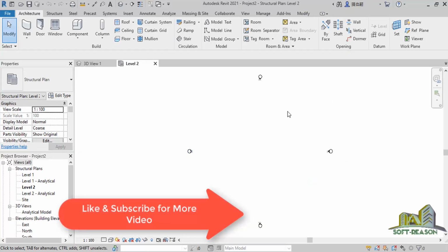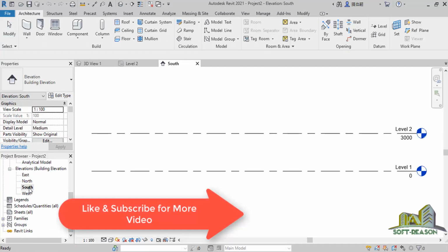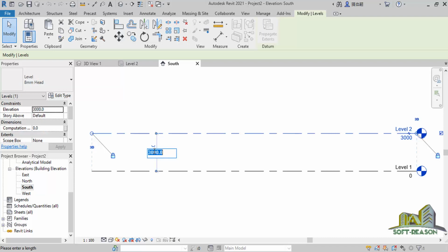So having created a new project, if I go to my site elevations, I will see my elevations. So I want to have more elevation. I'll click on this, the thickness of my raft. I will use 300. Then I'll click outside of it.